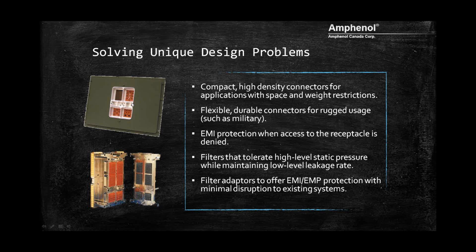What you can see here is we're working with one customer who was concerned about EMI windows around the connector. And obviously, if you have any type of hole in an LRU, you have the potential for an EMI window. You can solve that by applying EMI gaskets or EMI coil springs or a wide variety of solutions. But this one particular customer had this problem, and we said, here's our solution. Why don't we build the connector as part of your panel?